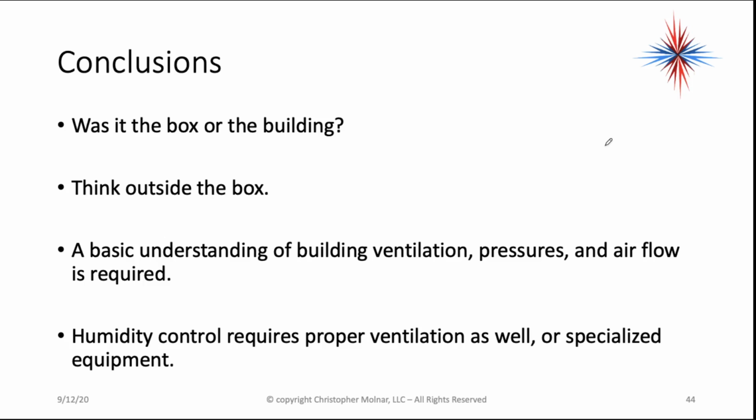You have to get rid of the humidity, or you have to have specialized equipment that can handle dehumidification in an enclosed environment. That would be like a standalone or a tied-in dehumidifier. Standard air conditioning requires that we do have some ventilation. It's what it's sized for. This equipment is not sized or designed for an area with no ventilation.